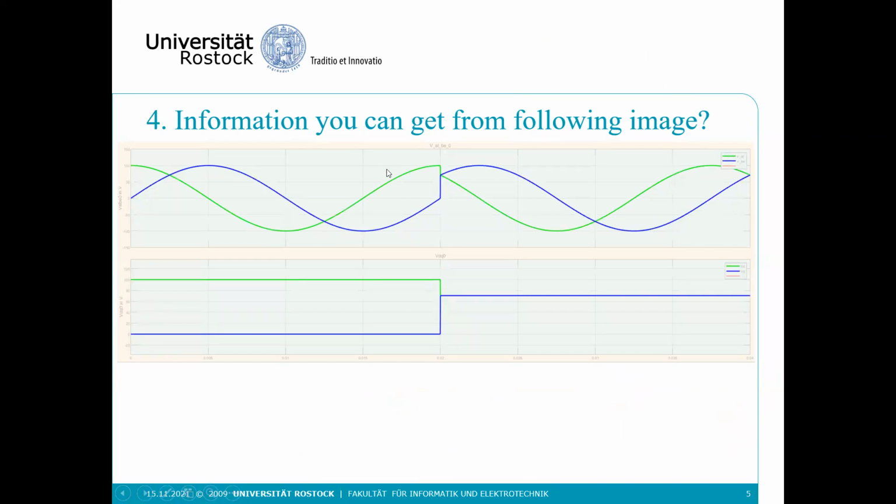This is the same DQ graph. And again, as usual, green is your alpha, blue is your beta, and this time is 0.02, and here green is your VD and blue is your VQ. Now you tell me, we had a question whether we had a phase jump in the alpha beta frame, or in the ABC frame, or in the Park transformation angle. Now, which one do you think it is? If you just have to choose within two options,